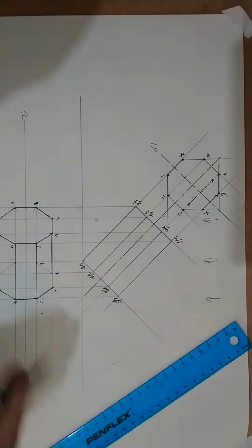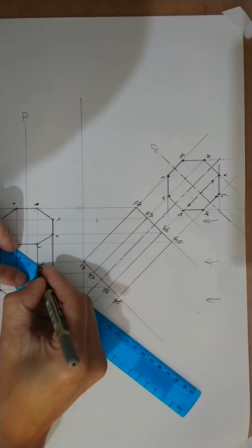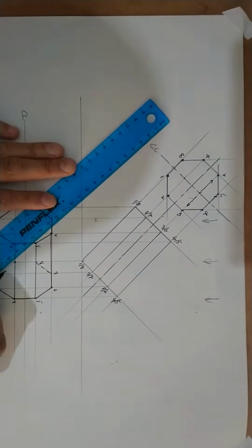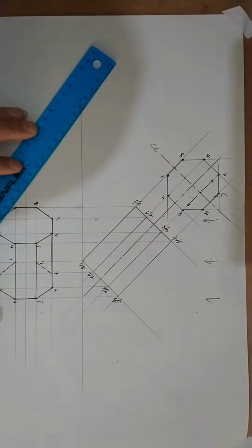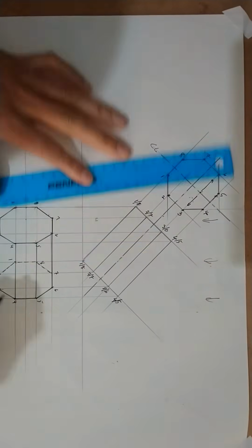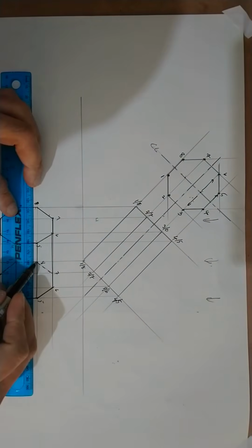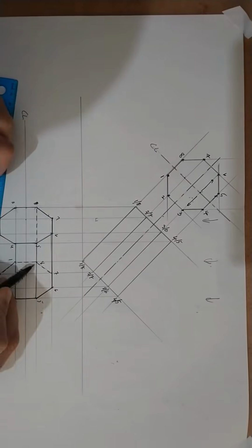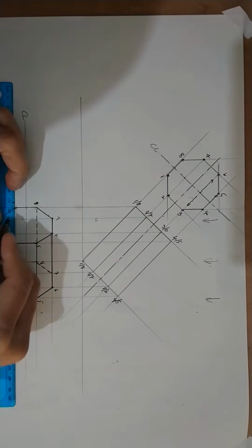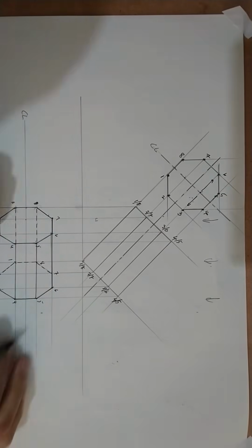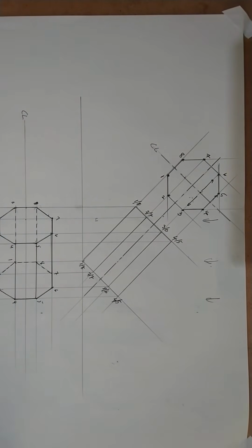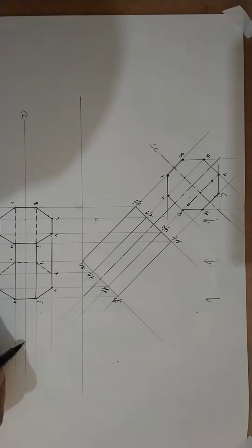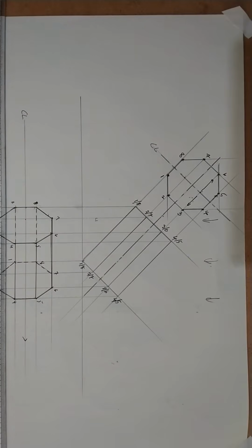If you need to put in dash lines, I suppose the dash lines will go here and here, because those are not visible, and there. These are the non-visible parts which I can't see, and the dash line will be under that line, but it will come out connecting number 8 to number 8, and then number 1 to number 1, which I cannot really see. The dash line will continue underneath, which we can't see at this moment, and that concludes your top view. Now remember, this is your center line here. So all I'm going to do now is create another center for my left view.